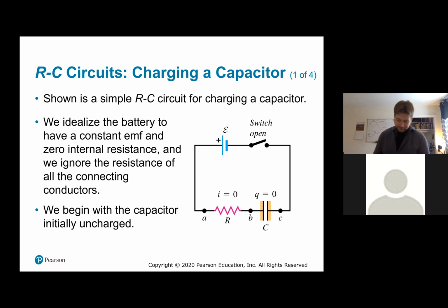Because remember, the greater the current through the battery, the less potential difference we actually get because we have to spend more energy pushing through the internal resistance. The less potential difference, the less energy per unit charge, and the less bright is the flash, because we're talking about a decreased transfer of energy.